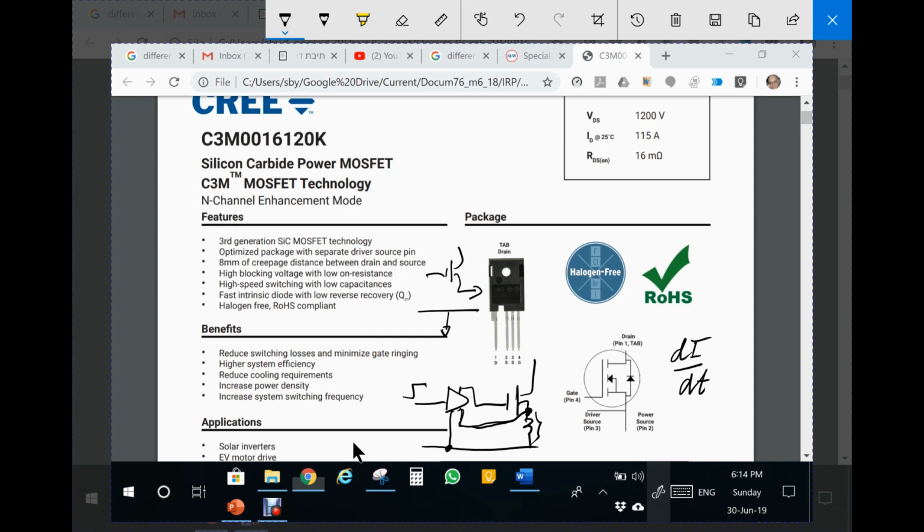Now, obviously, there are still some leakages involved because of the inner connection of the die, etc. But of course, the problem is one order of magnitude less than when just connecting this to ground without having the Kelvin connection. So this is the reason for this connection here, which is now fairly common at high power devices.